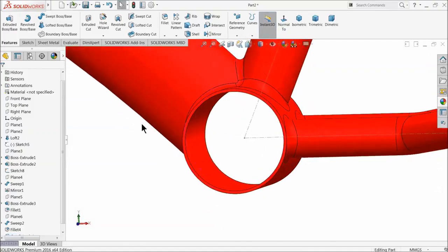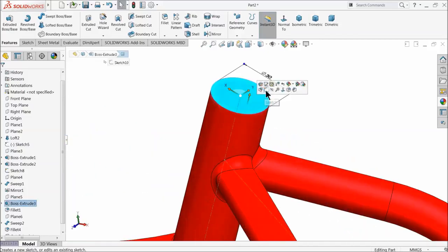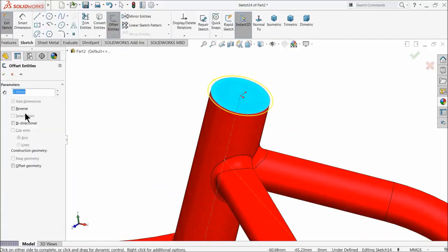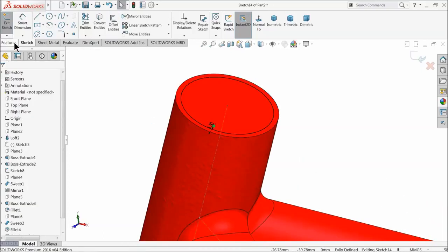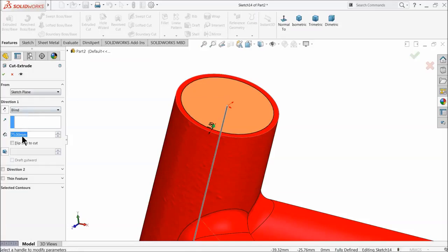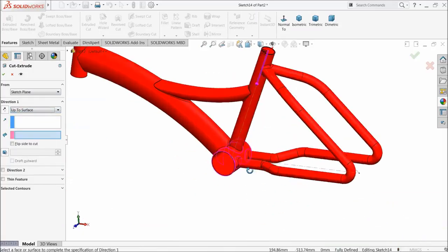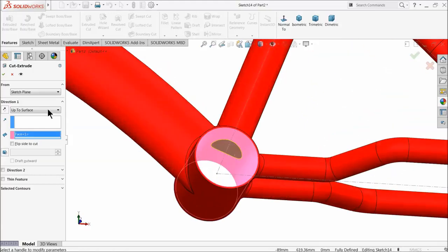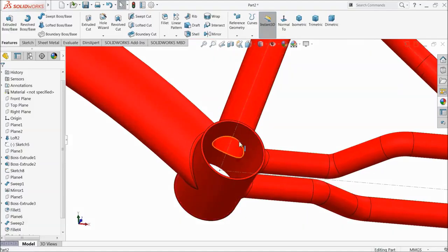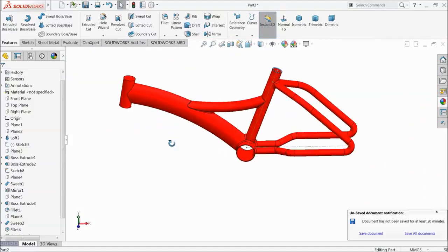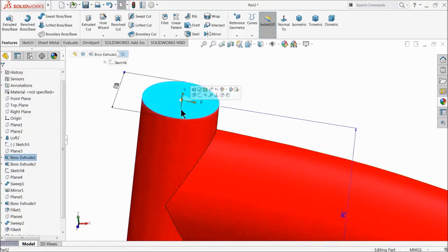Okay. Now that's it. Now the same way we have to do from this top face, sketch, offset, 1.5 inside, reverse. Okay. Go to feature and select extruded cut and here choose up to surface. And let's choose the surface. Select this inside surface. Okay. Now see the hole is exactly up to this surface. Now let's try this one, the last one.